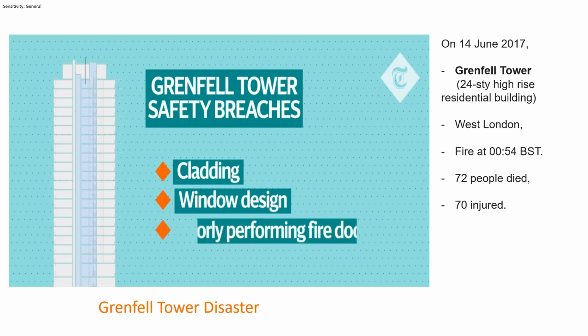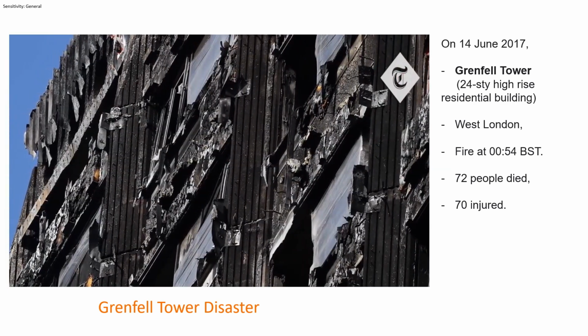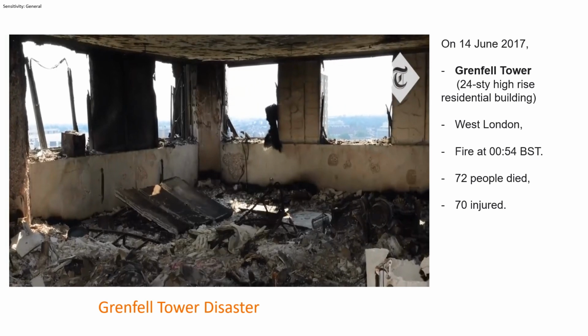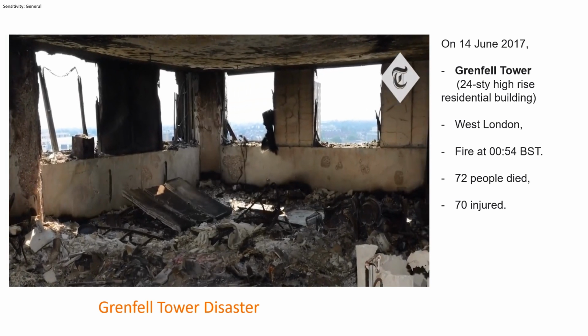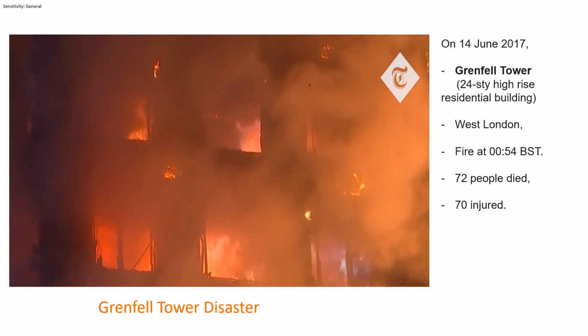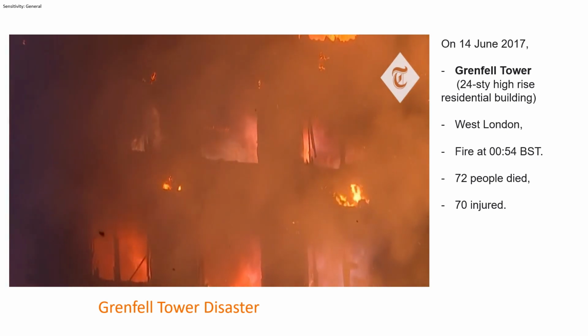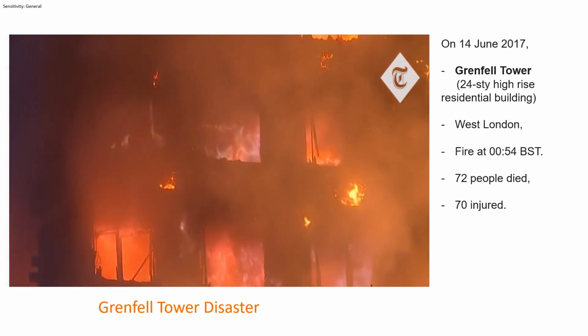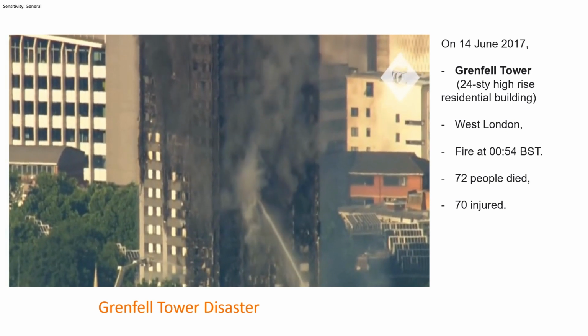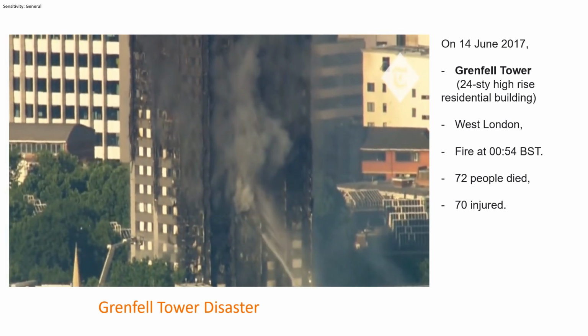Poorly performing fire doors contributed significantly to the spread of smoke and fire to the lobbies. And some doors failed to self-close after an occupant escaped. This allowed immediate spread of fire and smoke. Lastly, firefighters may have contributed to the spread of fire and smoke into the stairwell by leaving doors ajar as they fought the blaze. Many more questions still need answering as to how a small domestic fire spread so rapidly and so catastrophically.